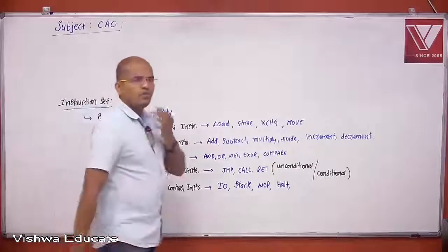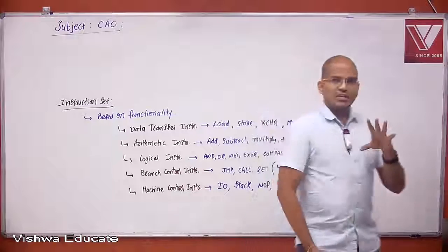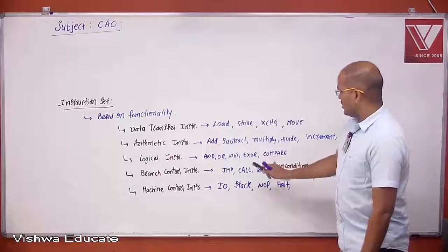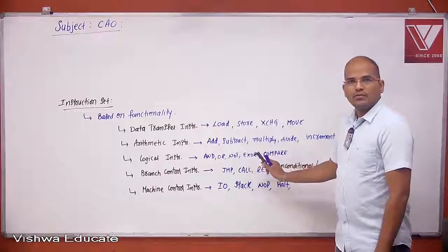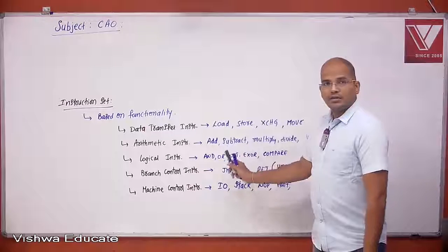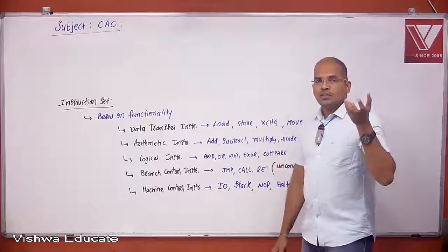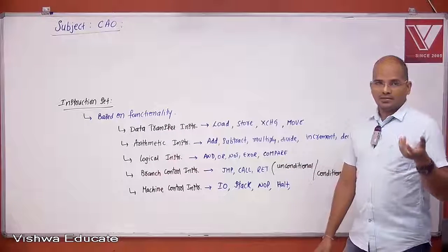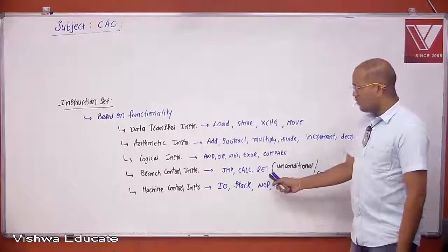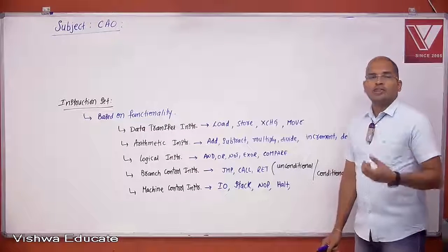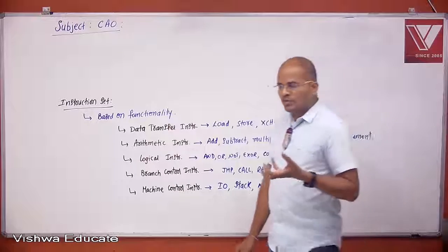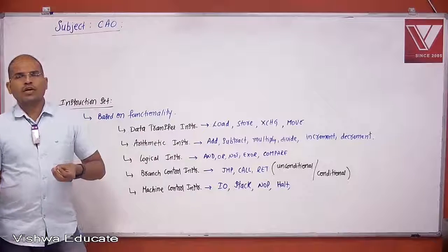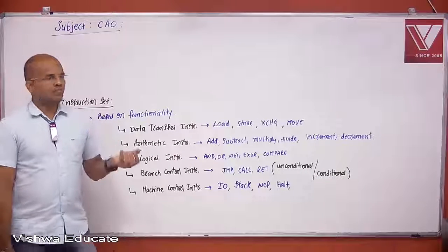From this concept, few things to be kept in mind. First thing is, there is a difference between compare and subtract. The difference is, in subtract, the initial value of the registers are lost, whereas in compare, the data retains. Second thing, how do you perform branching? Based on conditions, we generate conditions based on the flag values. If flag value is something, we do a condition. If it is something, we have a condition.